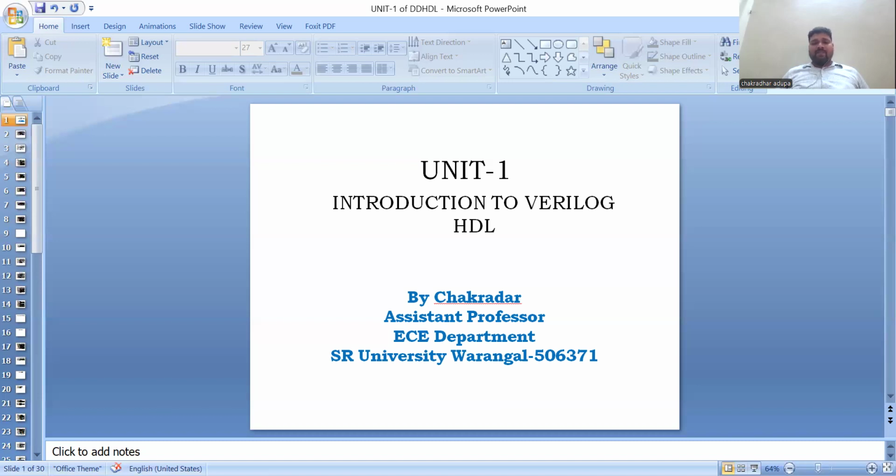You can expand this idea to more complex designs by writing test benches that cover corner cases and edge conditions for the function you want to verify. Would you like to proceed with a specific Verilog design? If you have Verilog code ready, then we can share a tailored test bench. Anyone comfortable with Verilog coding can easily write the test bench, because the test bench involves the set of possible inputs, and based on that, the design is simulated and its functionality is checked with corresponding outputs with respect to the stimulus.